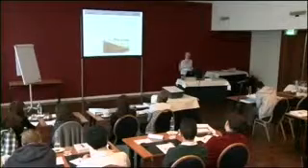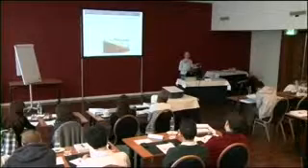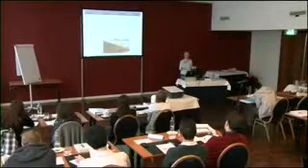And for a time it has been 2, but it's of course based on the property you're considering. Is it strength or is it durability? And at what time you're considering. Is it 1 day, 2 days, 28 days? Which value is reasonable? And the efficiency factor describes how much, if I add 1 kilo of the material here, silica fume, how many kilos of cement can I take out of the mix and get the same property?